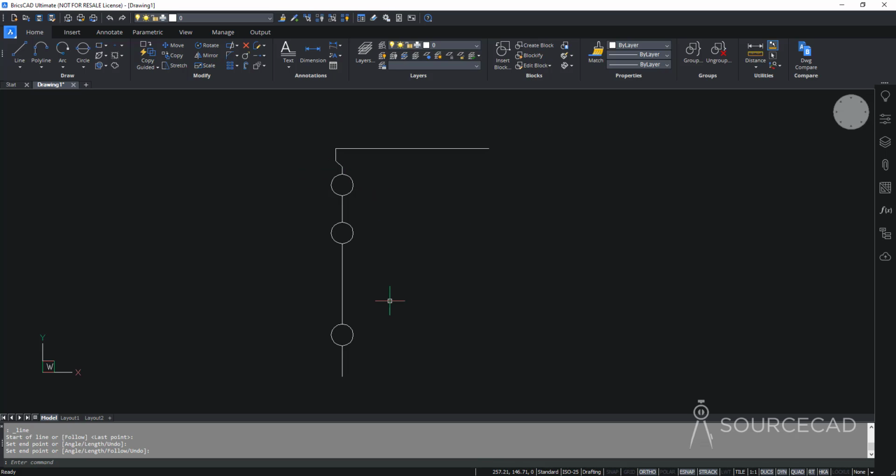Now let's add more detail to this drawing, and for that I'll just go to this trim tool and press enter and trim all these extra arcs. So we just don't need that, so I'll just delete it. Now we have the arc that we need. Okay, the next thing is circles here. And to do that, to add the circles, I'll first start with a construction line. So I'll go to line, I'll click right on this midpoint, and then I'll make a line of length 19.5 units. So 19.5 and enter.